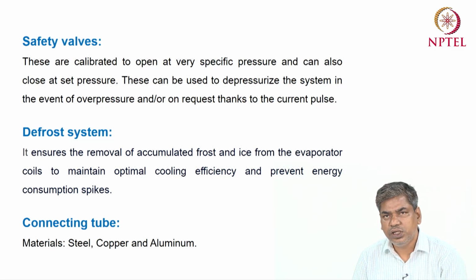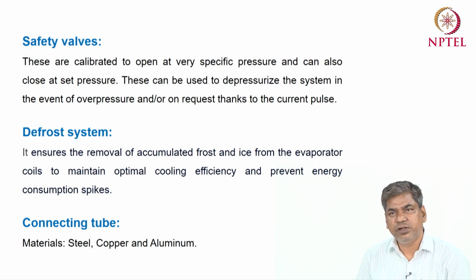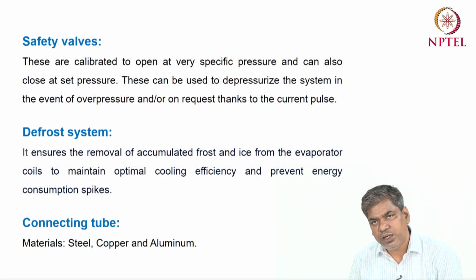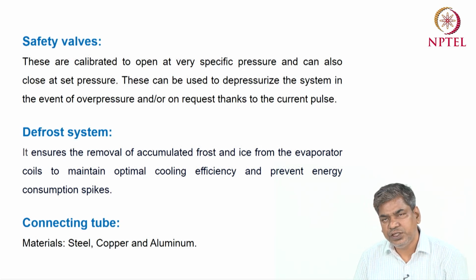Okay, so in this case, what is happening is that the moisture in the air will form ice, or frost. That ice will block the passage and block the system. You can see in a household refrigerator, ice is formed in that zone, and that ice makes a layer on the evaporator.